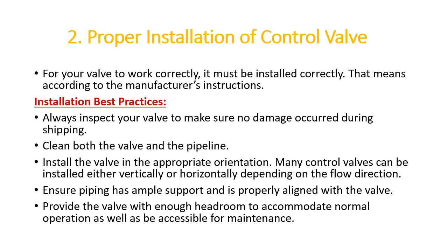You can check the tightness of the seat and everything. This will help you at the time of commissioning. If you can check at least some 50-60% of the valve in the workshop, it will require less time during commissioning. Also, the control valve should be the last installed object in the line.